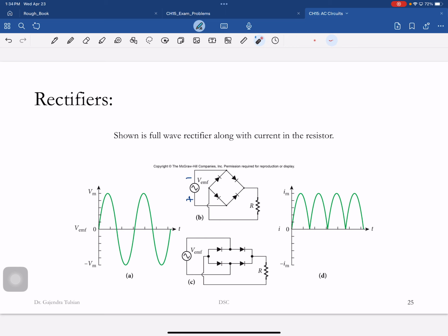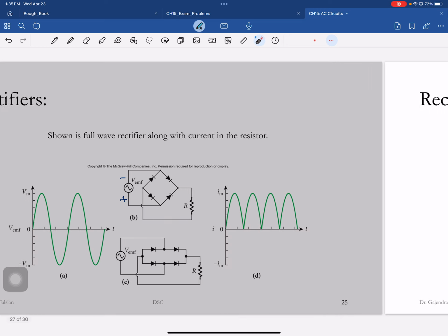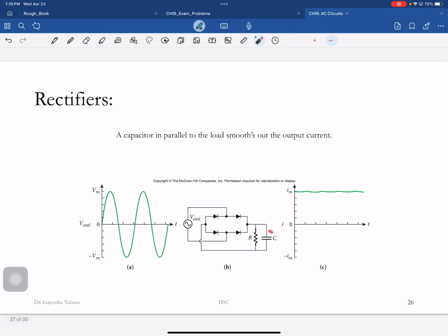But her laptop is very finicky. It doesn't like this. What it wants is a flat 12 volts. So you've got to smooth this out. What you do is put a capacitor, and now the voltage across this is that.